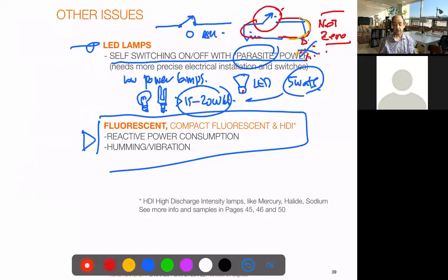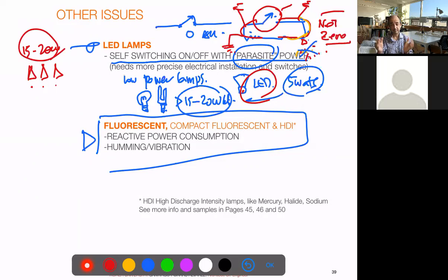One is to have a better switch and more strict network regulation, which is difficult because this is not a closed circuitry. It is connected to ground. And you have many devices which accumulate power. You have televisions. You have maybe stereo amplifiers which have a lot of condensers. So the electricity keeps moving on the network a little bit. The other way of doing it is to use not a simple LED, but luminaires with a set of several. So you have at least 15 to 20 watts. And that's enough for closing that circuitry and not making it work, right? So you have two possibilities.